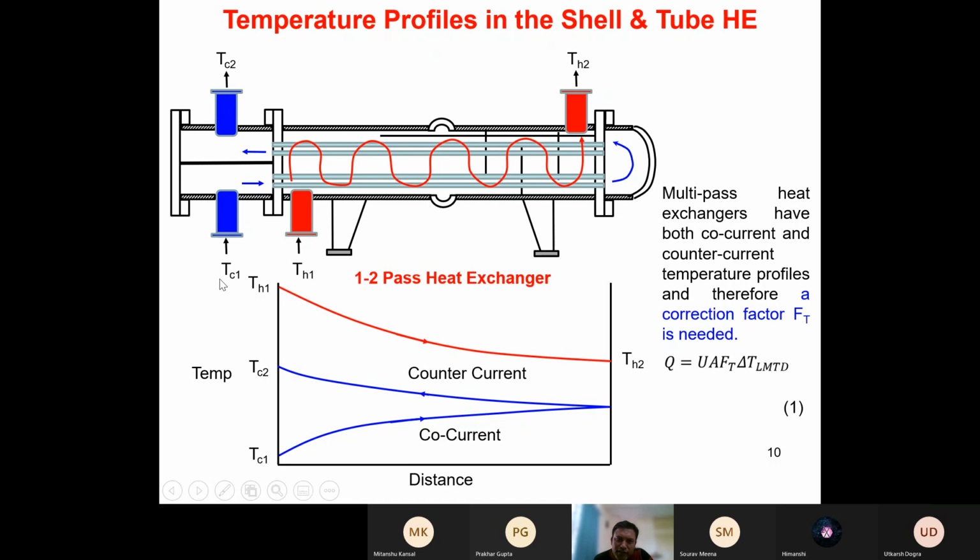Whereas the cold fluid is entering here, passing through this tube, changing direction and coming back through these tubes, and finally coming out from the tube like this, isn't it? Coming out from this nozzle like this. So here you can see that the cold fluid is having two passes. One pass is this and the second pass is in the reverse direction. Can you see the point now? Is it clear? Yes, sir. Now it is clear. Now let us plot its temperature.